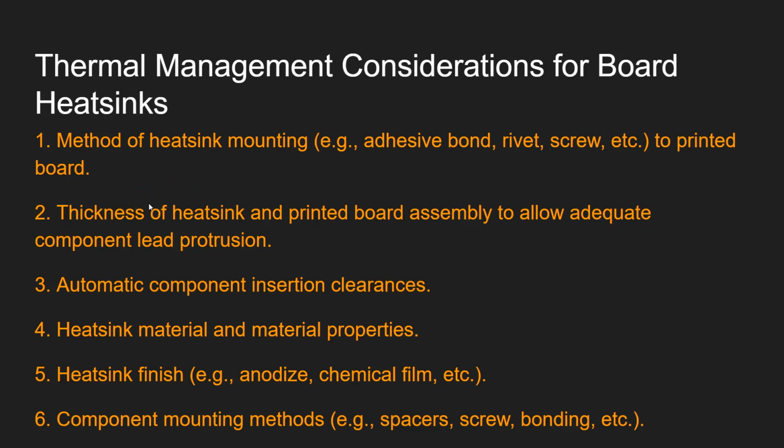Thickness of heat sink and printed board assembly to allow adequate component lead protrusion and automatic component insertion clearance, heat sink materials and material properties, heat sink finish, for example anodize, chemical film, etc. And component mounting methods, for example spacers, screws, bonding, etc.